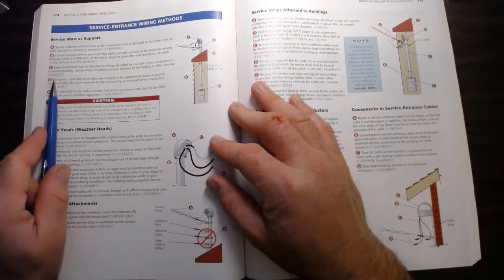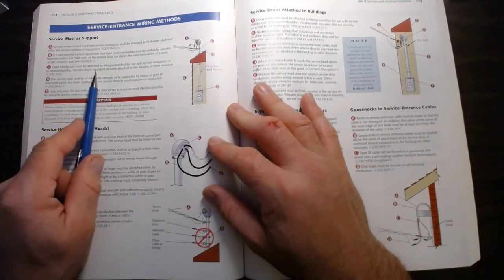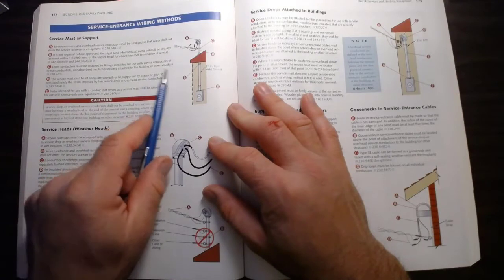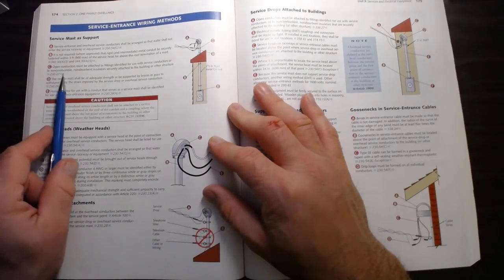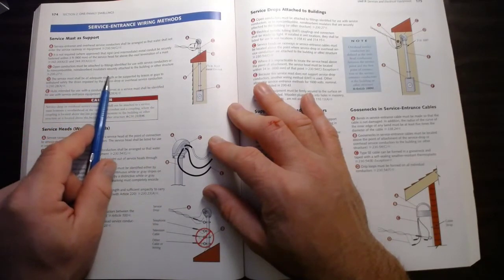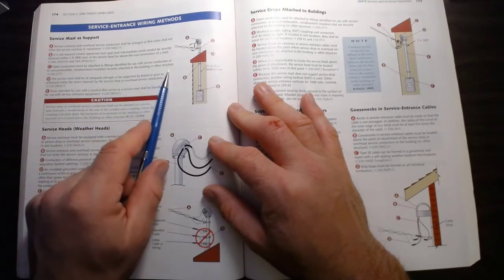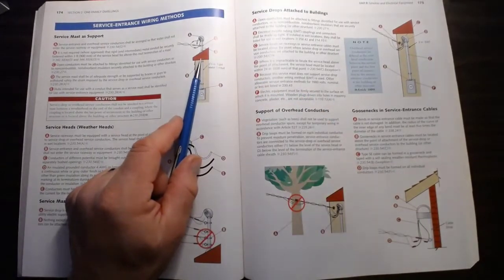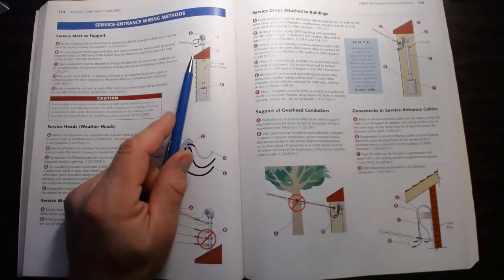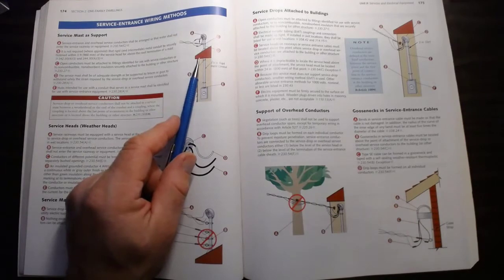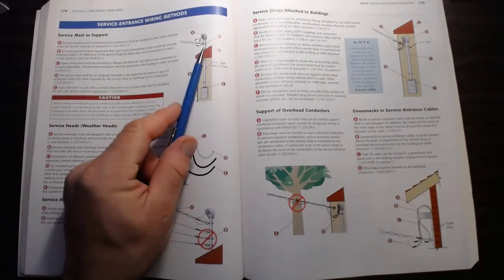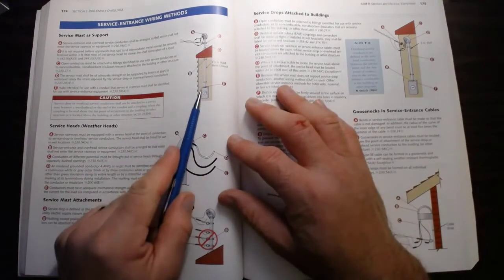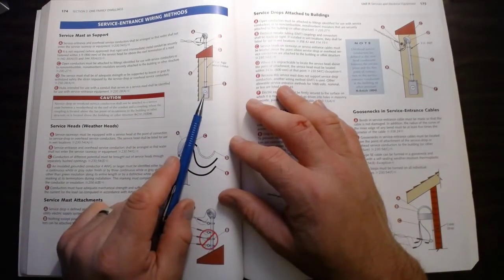So the next thing we want to look at is open conductors must be attached to the fittings identified for use with service conductors or a non-combustible, non-absorbent insulator securely attached to the building or structure. So this is giving us two options. Now the utility is going to also govern that. They may say, no, you cannot attach the triplex to the house or the structure. You need to attach it to the riser, because the riser is going to be stronger in how it's connected.